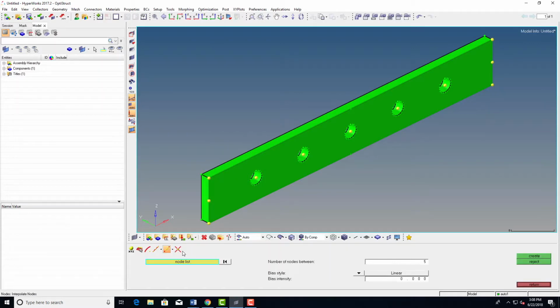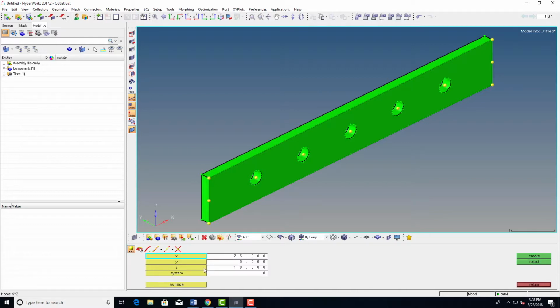Okay. So now we're going to create the top T of our T-beam. So we created the side, now we're going to create the rest of our cross-section. So we're going to start at x is 0, or we can start at x is 75 across the beam, just to show you that you can also drag the solid in the negative x or x-axis. So we're going to start at x is 75, y is -1, and z is 10. Excuse me, messed up. Z should be 11.